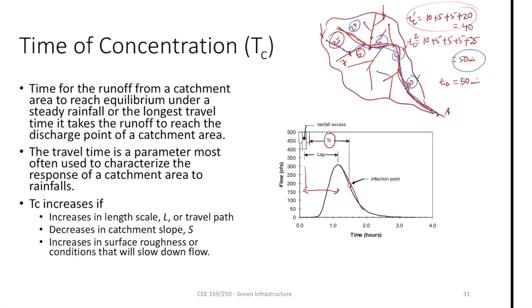So your goal as a green infrastructure designer is to increase that time of concentration. When you increase it, the peak slows. That's the whole thing called flattening the curve. If your design at that location makes the time of concentration very long, then obviously it will be a good design. So just know these things. This is relevant for the quiz.